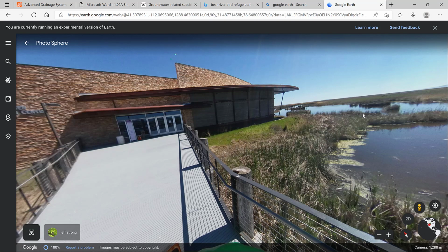Anyways, it was interesting that when you switch over to the permanent one, it's not as deep as the one you want for construction, and so that water table starts to come up, and then you're dealing with another problem, right? It was a day to remember, sloshing through there, getting all the pumps that we had operational and pumping out the basement, and then figuring out how we were going to seal that. I think the first thing we did was switch back on our dewatering system, bring the water table down, pump out the basement, and figure out what we were going to do with the hole around that fire sprinkler pipe riser.